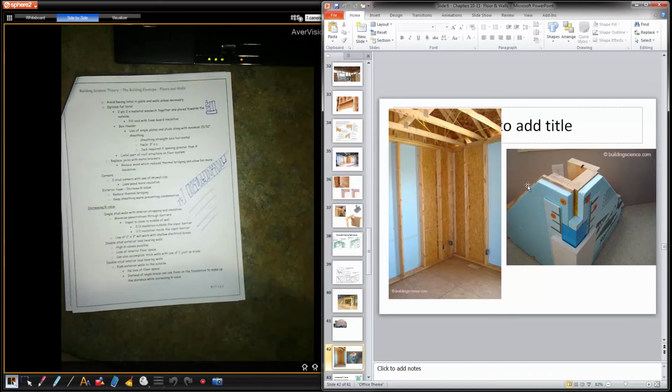So in this case they have OSB sheeting, so that's what's happening in the corner there. That's what I was talking about before. This is probably 2 inch foam. Then they went with 1.5 inch foam with a sheet of 1/2 inch or 7/16 OSB, making up the 2 inch. Right, so that's a 2 inch block, which would be representing this. So they fill in the corner with that leftover blocks, and then they seal that with a loose skin product that's compatible to the foam, so it doesn't break it down. And then there's a large trim board, so they flared it out with foam.